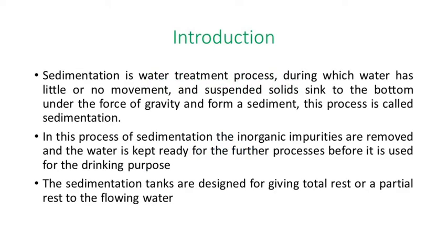So what is sedimentation? Sedimentation is a water treatment process during which water has little or no movement and the suspended solids sink to the bottom under the force of gravity and form a sediment. This process is called sedimentation. As the name indicates, it is a process of removal of the sediment, or allowing that sediment to settle down at the bottom under the force of gravity. That is the process.